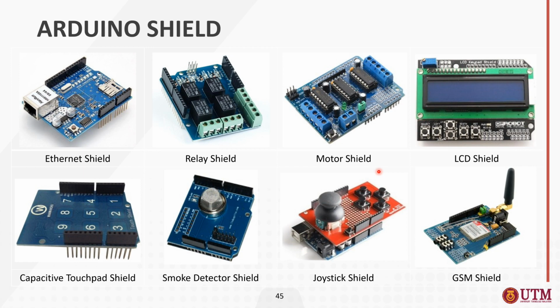Please be aware that if you want to connect your system to a motor, you must first connect it to a motor driver, because you don't want to damage your Arduino. The motor has the tendency to give back voltage or back current, and that can destroy your Arduino.